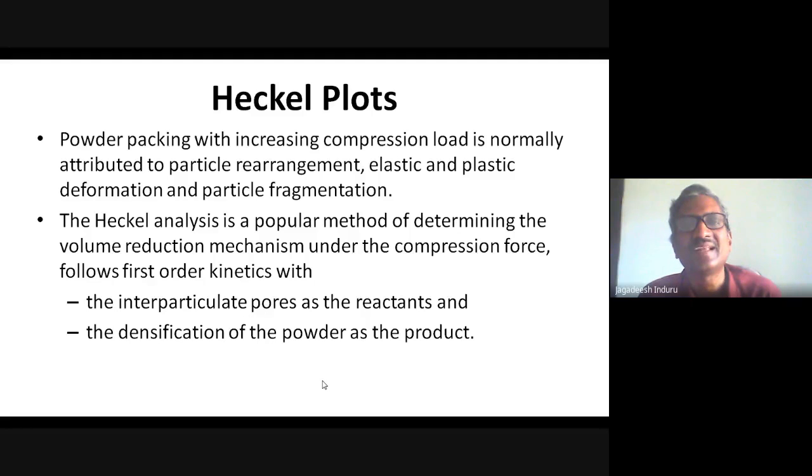After particle rearrangement, there is an elastic deformation, but the elastic deformation does not result in any net size reduction or deformation. But when you apply force beyond the yield point, it will undergo plastic deformation. This plastic deformation is an irreversible phenomenon, and the powder is broken and getting joined, and you make a tablet.